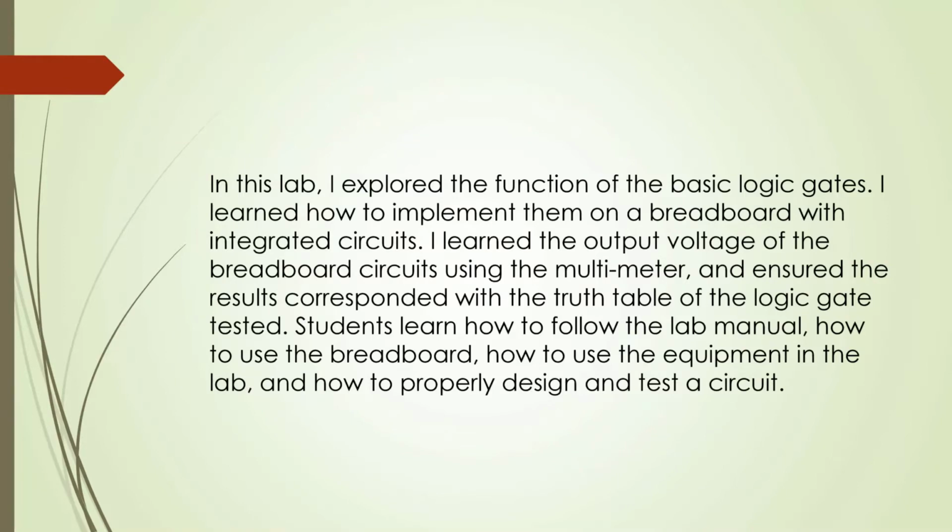In this lab, I explore the functions of the basic logic gates. I learn how to implement them on the breadboard with integrated circuits. I learn to measure the output voltage of the breadboard circuit using the multimeter and ensure the result corresponds with the truth table of the logic gates. Students learn how to follow the lab manual, how to use the breadboard, how to use the equipment in the lab, and also how to properly design and test the circuits.